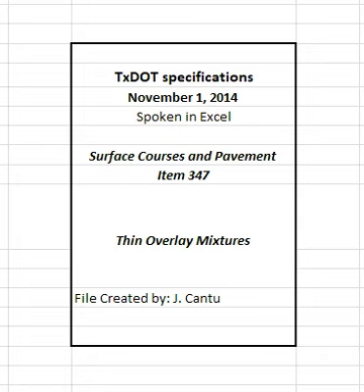4.4.2.1.6 Ignition oven correction factors. Determine the aggregate and asphalt correction factors from the ignition oven in accordance with TEX 236F. Provide the engineer with split samples of the mixtures before the trial batch production, including all additives, except water, and blank samples used to determine the correction factors for the ignition oven used for QA testing during production. Correction factors established from a previously approved mixture design may be used for the current mixture design if the mixture design and ignition oven are the same as previously used unless otherwise directed.